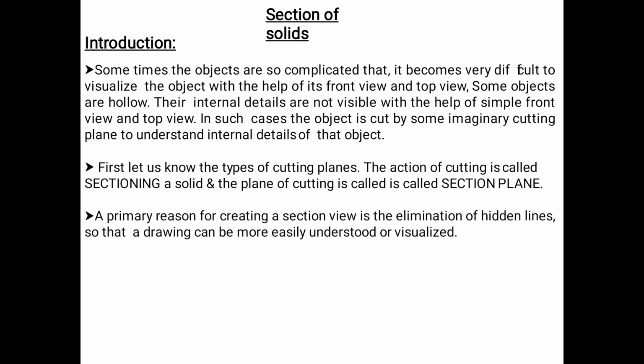Today we are going to discuss sections of solids. Sometimes the objects are so complicated that it becomes very difficult to visualize the object with the help of its front view and top view. Some objects are hollow. Their internal details are not visible with the help of simple front view and top view. In such cases, the object is cut by some imaginary cutting plane to understand internal details of the object.